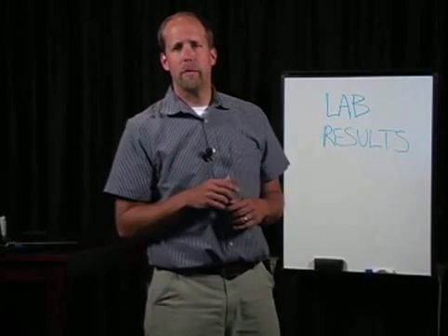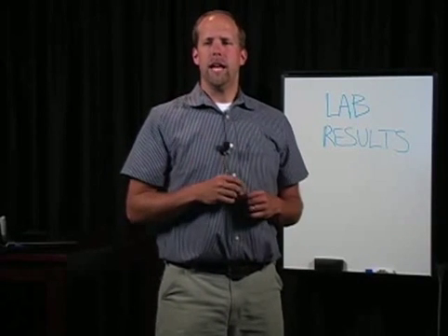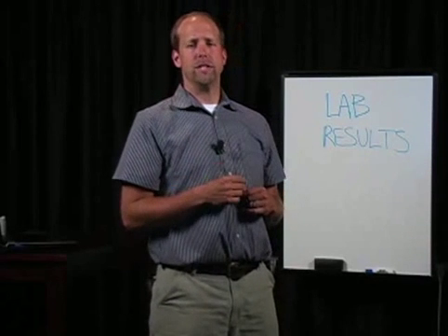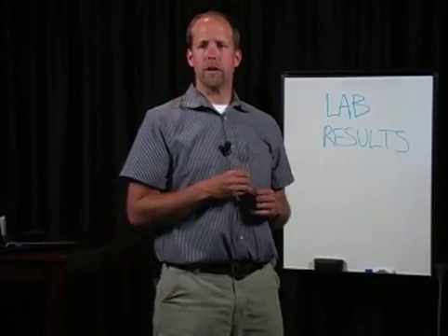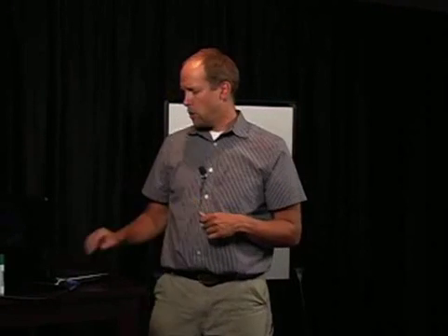Once the mold problem is identified and the mold remediation is complete, then the type of mold and the concentration levels of mold should be similar. After remediation, the types and concentrations of mold in indoor air samples should be similar to those in local outdoor air.